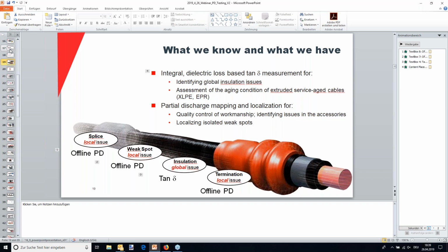These numbers that I'm telling you are the stuff that we got back from the utility companies and what we see in the field. I intentionally did not put up a table in this presentation because then I'm afraid people run around and say, oh, Megger said. We have this from at least 3-4 very different utilities, and they're all similar and they're all dissimilar to a certain extent. In the standard itself, in IEEE, there is no absolute value established, but we know from experience that a few hundred picocoulomb is typically what you see, and then it goes up into the thousands.